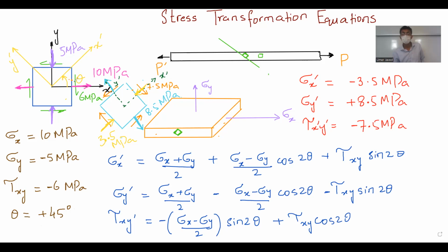Because I tilted it to 45 degrees like this. I tilted it and I have to forget the old one from now onwards. This is my new element. I tilted it at 45 degrees and now the answer is negative 7.5. I will focus on this surface only first, and I will put a downward arrow here, an upward arrow here for clockwise to indicate negative 7.5, and subsequently anti-clockwise here. If you ask why we focus on this surface, it is because we always focus on the theta equal to 0 surface; you tilt it, this surface becomes this surface, then I started focusing here.